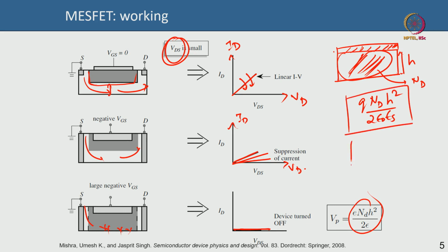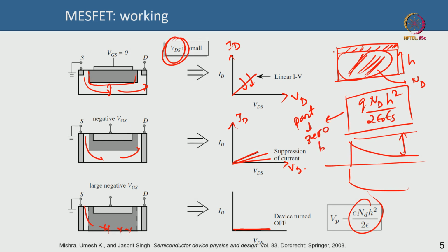So, this is the total voltage drop that will happen. If you remember, your Schottky barrier looks like that, correct. So, this is your voltage drop. So, to deplete this entire channel, this is the voltage drop you need to sustain across the material, across the channel. However, a part of that is already depleted at 0 bias. At 0 gate bias or at equilibrium, the Schottky metal already depletes something, right. So, at 0 gate bias you have a certain built in voltage. Suppose the built in voltage is 1 volt. So, that is the 1 volt that is dropping even at 0 gate voltage.